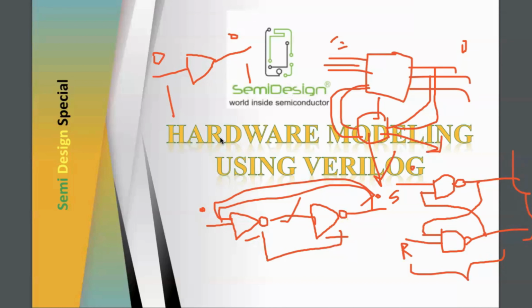To avoid the race conditions, and also, in latches, the output depends on every change of input. Whenever the input changes, it automatically reflects at the output. But in the flip-flop, it doesn't automatically reflect at the output. Even if the input changes, it waits for the edge trigger. Only on every edge will the output change, right? So that is the difference.